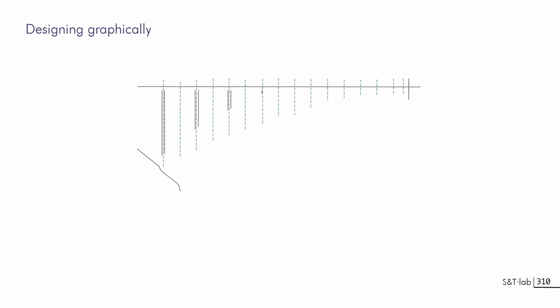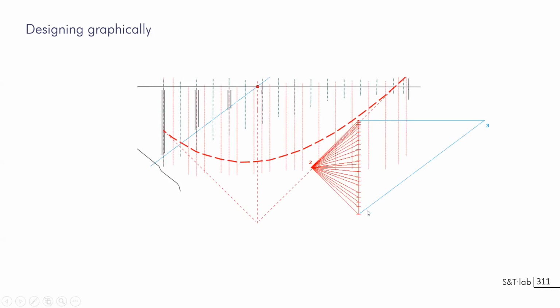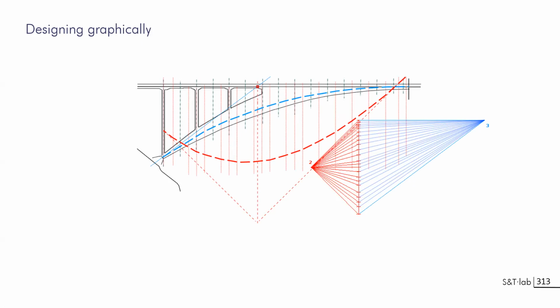And in this case, you just have the line of action of the loading. You can take a first loading and you will be building the construction as you know. You get the pole and the direction from the support and start building this thrust line. And once you have this thrust line, you can balance the successive sections of the arch and of the deck to correspond to the thrust line.